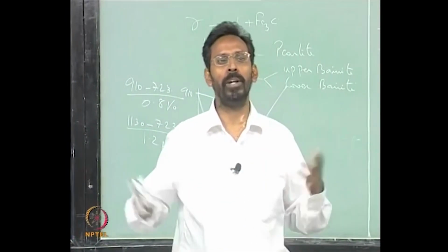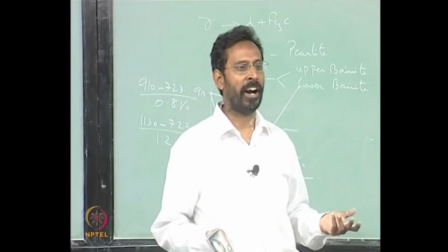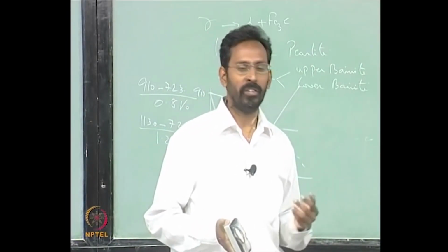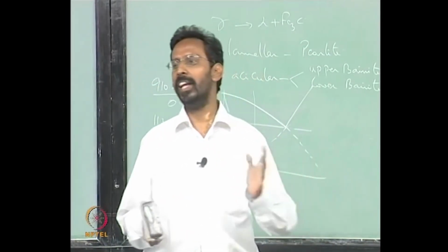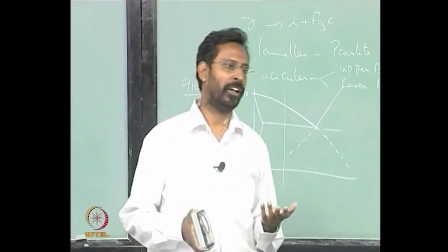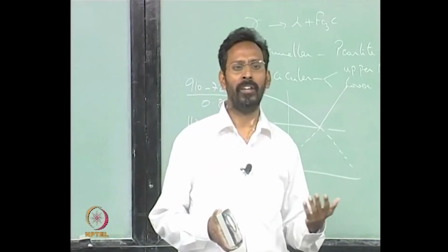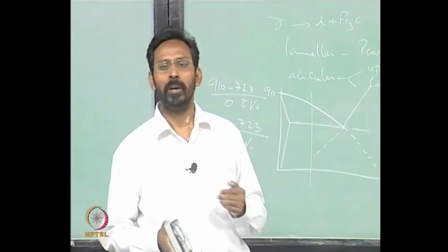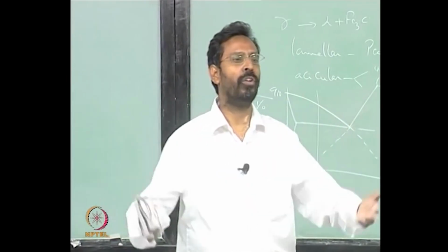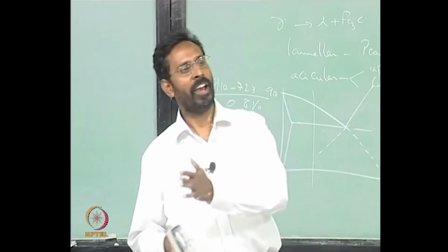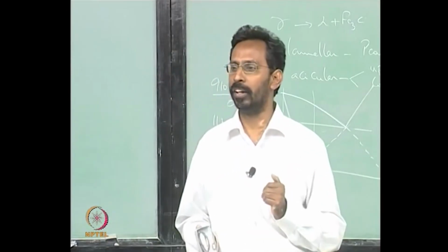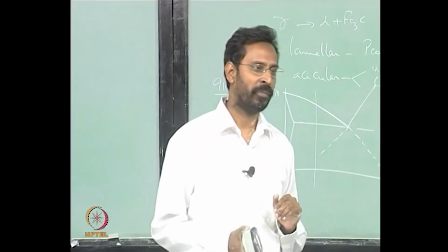It is like having too many dislocations, you have work hardening taking place. So similarly here, any alloy diffusion or chemical diffusion, not self diffusion, is going to be more difficult if you have the solute content higher. That is why chemical diffusivity, if you read about diffusion, is always a function of composition.